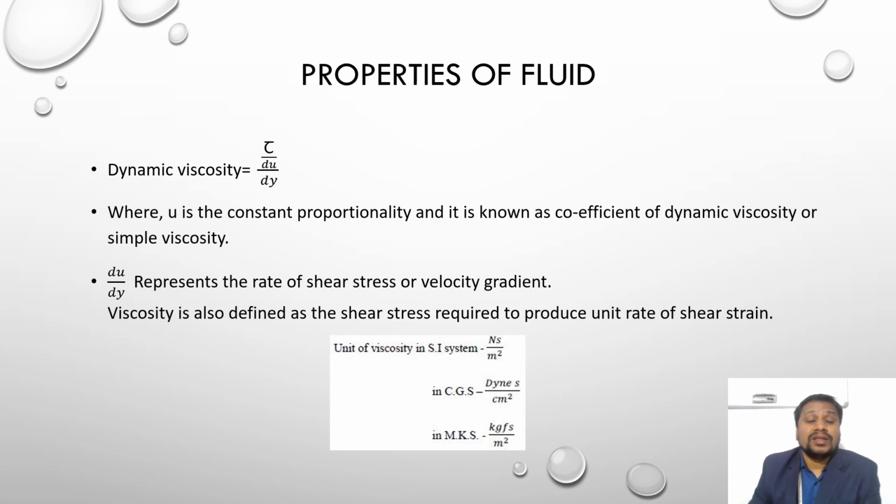Here another law is there, Newton's law of viscosity. Newton's law of viscosity states that the shear stress produced between two layers is directly proportional to the velocity gradient. Tau is directly proportional to du by dy. It is known as Newton's law of viscosity.